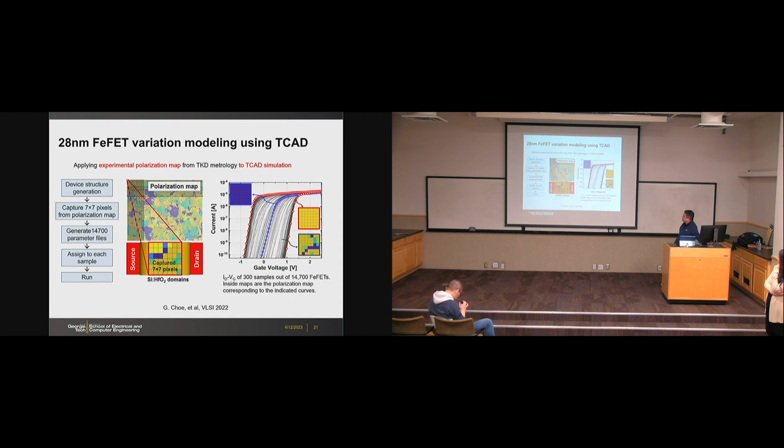Yeah, that's a very good question. If you make a FET, then you measure the drain current, right? So you need to have distinguishable states. From the drain current, from the memory window point of view, let's say you have 300 millivolts between the 2 threshold voltages, you can distinguish that. Of course, you need to tighten the distribution. So you need a gap of, let's say, 300 millivolts between 2 adjacent states. And actually that's a number for today's commercial NAND flash for the TLC, triple level cell. The adjacent threshold voltage step is about 300 millivolts.